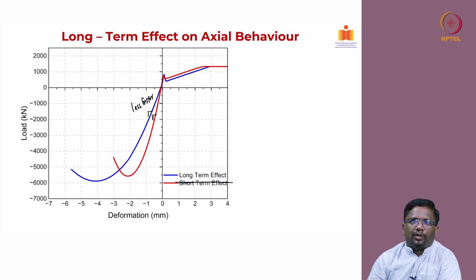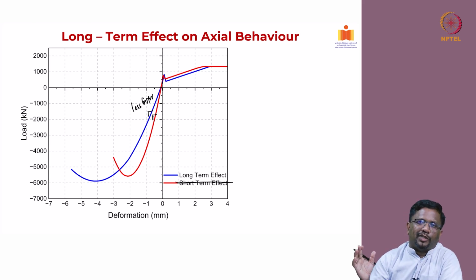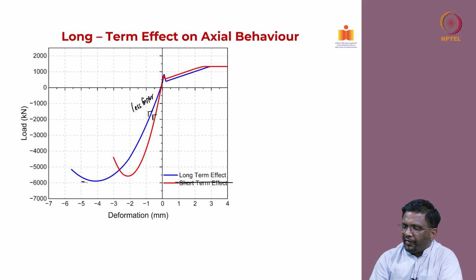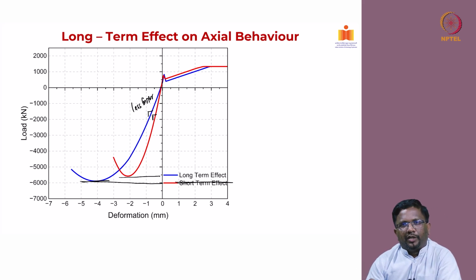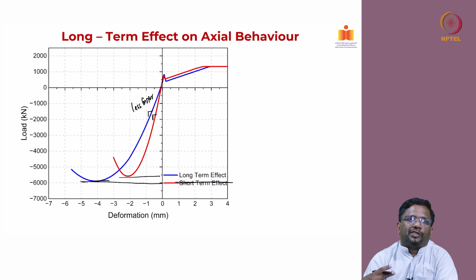If you consider the long term effects, the member response becomes less stiff. But one benefit that you can see from considering the long term effect, what is that? Your compression load actually goes up. So, in a way, it is offsetting the detrimental effect of pre-stressing on the compression side, right. So, this is one of the beneficial effects of considering long term effect in this example that